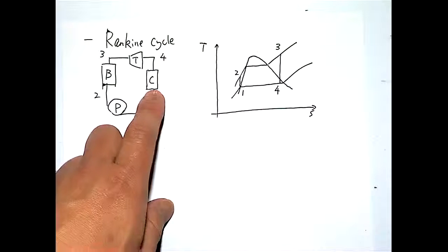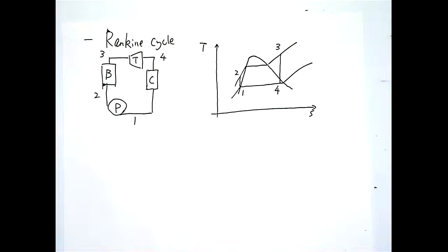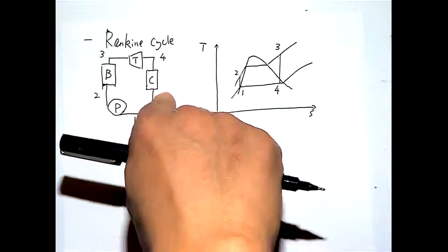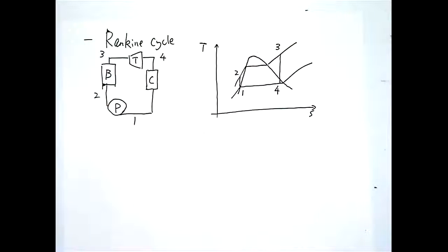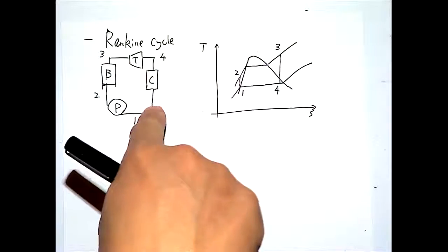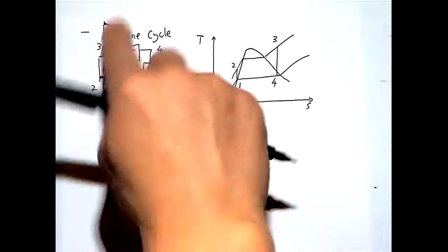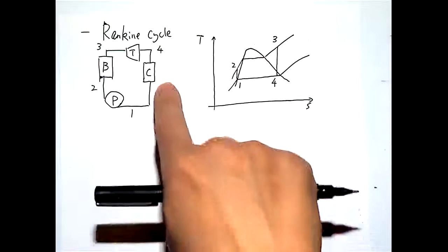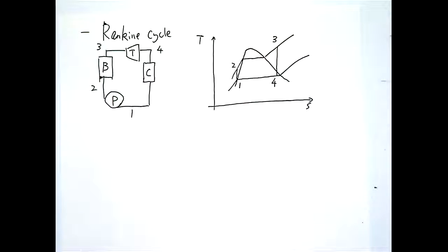So often, if you consider the 1 atmosphere pressure corresponding to a boiling temperature of 100 degrees C. If you want to have the condenser operating at any temperature below 100 degrees C, which means this condenser needs to operate at a pressure below 1 atmosphere, which means this needs to be operated with vacuum. So they become a vacuum chamber. And then the condensed water is going into the pump again.